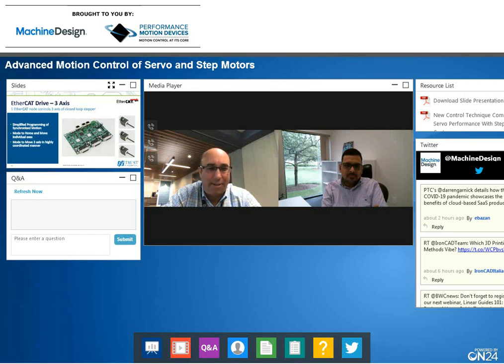Our approach tends to be, we have our favorite ARM-based TI processors that we use for host processors. They talk to PMD chipsets. We tend to sprinkle a handful of them around, and between our application engine and our libraries and working with the PMD side for trajectory algorithm control, and then marrying between the 2 companies at different times using different techniques for the drive side, we get the best of both worlds.